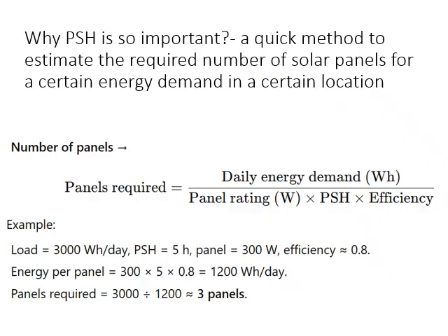Why is PSH so important? Why do we need to know that? Say, for example, you want to install some solar panels in an area. You need to know how much the solar intensity is and what your energy demand for the house is, and in terms of your energy demand and the solar intensity in that area, how many solar panels you need to install. So it actually gives us a quick estimate of the required number of solar panels.